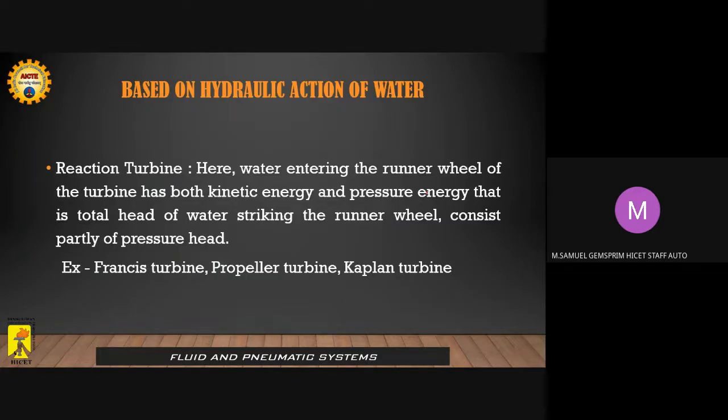Next, we move on to the reaction turbine category. In this reaction turbine category, all the other three turbines come under this category: Francis turbine, propeller turbine, and Kaplan turbine are the other three which we use in the reaction turbine category. In this case, we use kinetic energy and convert the hydraulic energy of water to mechanical energy.